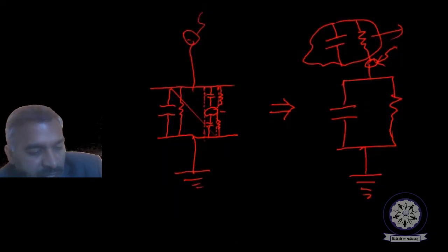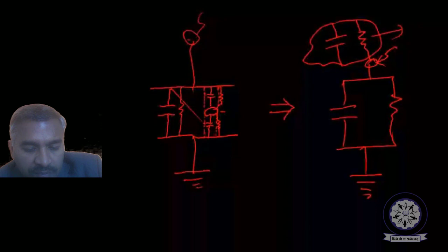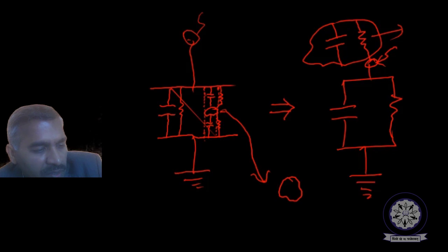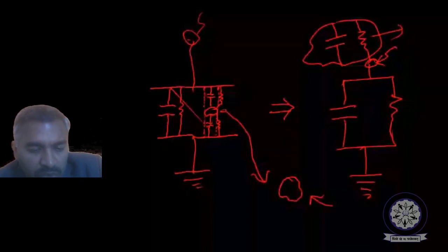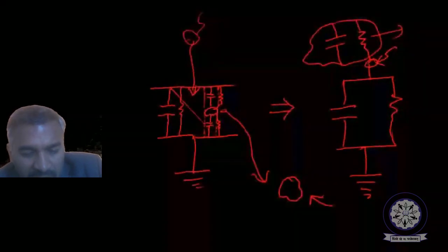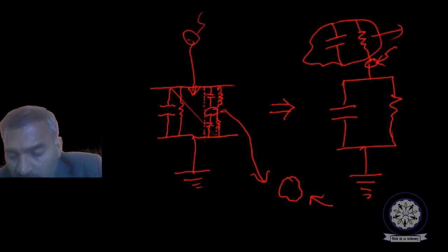But we will study what partial discharges are, etc., that occur inside these voids. Actually, power equipment is supposed to get damaged due to these kinds of voids. Of course, there are many popular theories. Some people will say this is the reason for failure, or protrusions from the electrodes, or treeing. It depends on the material also. Those concepts we will study.